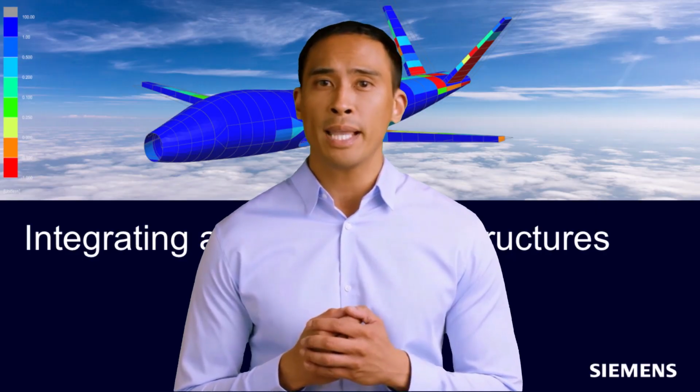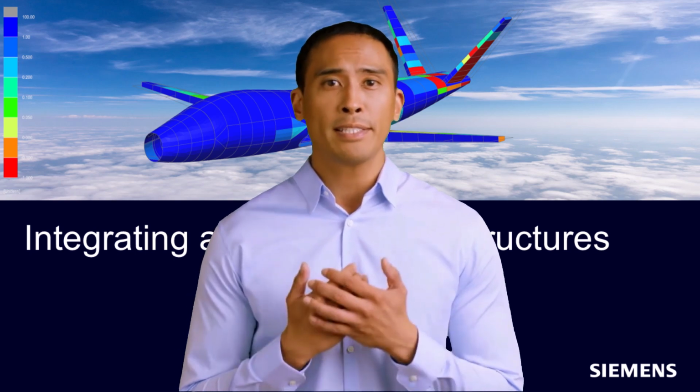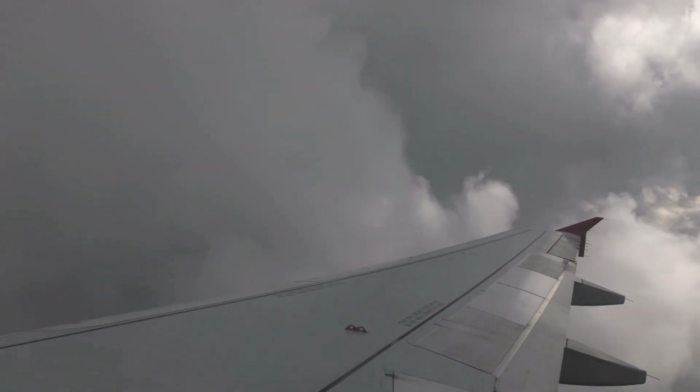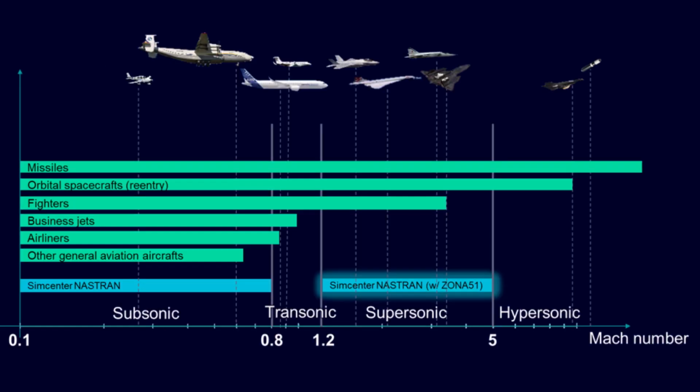Understanding aeroelastic behavior of aircraft, like flutter, is critical to airframe development and certification as well. Poor aeroelastic behavior can lead to loss of control of an aircraft, or worse, catastrophic failure. In this latest release, we have extended Simcenter Nastran's aeroelastic analysis capabilities to the supersonic range. This lets you analyze static and dynamic aeroelasticity and flutter above the speed of sound.